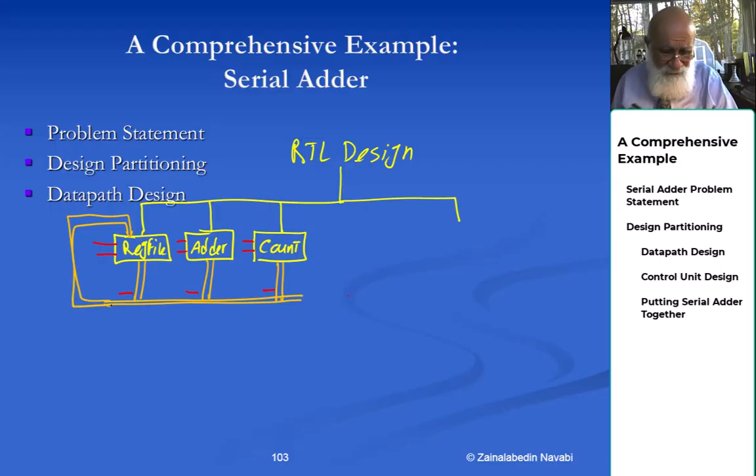So you are deciding on holders of data, register files, registers, and counters, processors of data, adders, subtractors, and also counters, because a counter takes the data and counts up from it, and also transmitters of data, which are the buses.